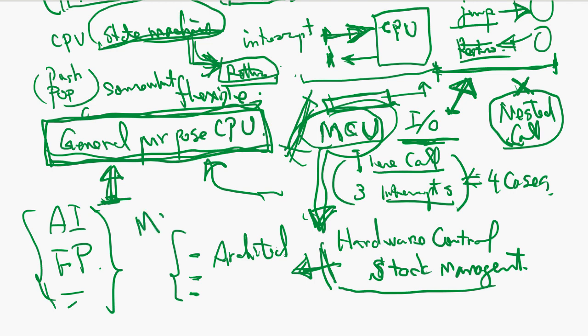General purpose CPU is pretty much established and there is not much change in this regard, but when it comes to AI, floating point, and other types of CPU, you don't necessarily need this kind of architecture. The general purpose CPU's functions have an all-different requirement. And an MCU doesn't actually need this complicated push and pop kind of interrupt. There is a much simpler way to deal with it, quicker, much faster, of course with less flexibility, because it doesn't allow nested calls.